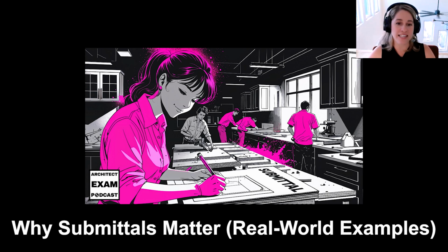So think of submittals as a building's vaccination record. They prevent serious problems before they develop. They're preventative. And if you skip them, you're taking a risk, and it could be an unnecessary risk with very severe and expensive consequences. So I'm sure you can think of some examples in your day-to-day or in your experience working in construction and buildings where a simple review process as a preventative measure could have saved the project a lot of time and money.